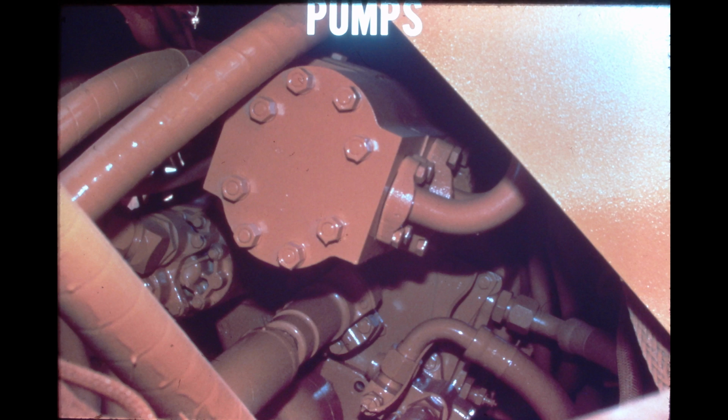The loader pump or switch pump can be the cause of a loss of power. The only way to check the pumps is to install a flow meter. The main hydraulic output for the 540 is 44 GPM at 2,500 engine RPM from the loader pump and 38 GPM from the switch pump. Remember that at 2,500 RPM, the flow would be combined loader pump and switch pump flow. So the diverter valve must be checked for proper switching before the pumps are flow rated.